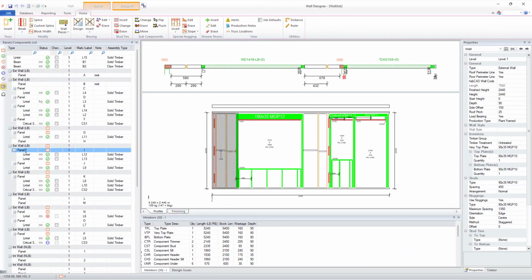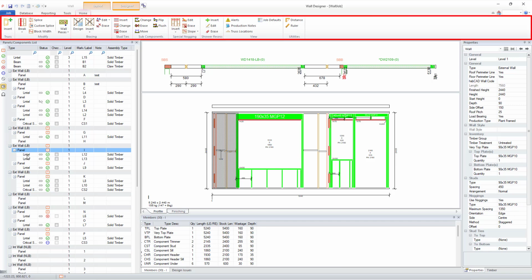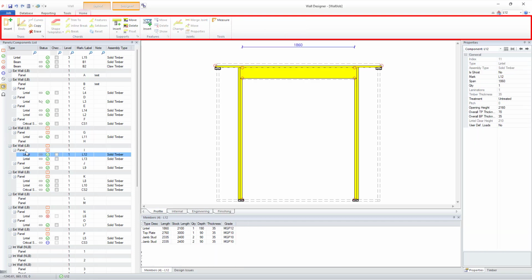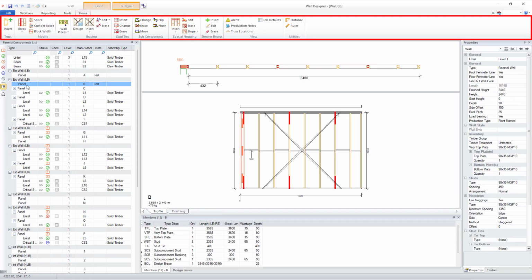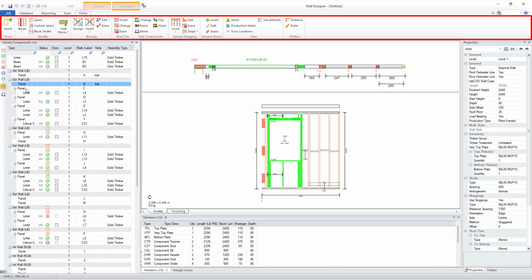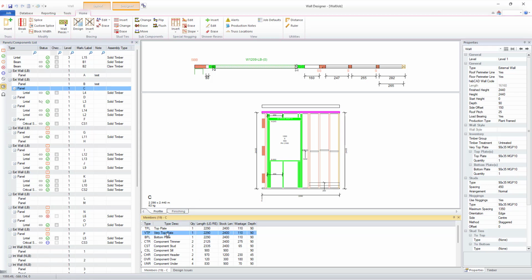Now, how do we handle designed elements and panels all in the one screen? You'll notice that the context menus around change as you select a wall or panel versus a designed element. Let's start with a panel. You'll see all the features you're used to seeing in the Panels tab of Wall Detailer in the menu here. Click in the Members list to see the corresponding element selected.